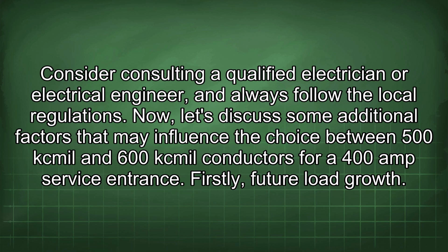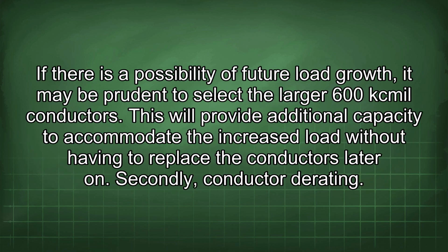Now, let's discuss some additional factors that may influence the choice between 500 kcmil and 600 kcmil conductors for a 400 amp service entrance. Firstly, future load growth. If there is a possibility of future load growth, it may be prudent to select the largest 600 kcmil conductors.